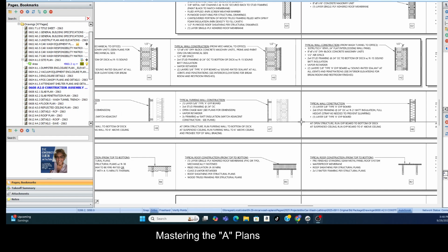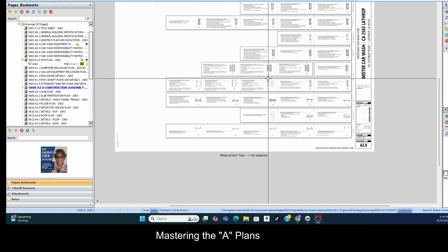And what we're going to do as the framer, what do we have to do? The floor plan is going to give us how many linear feet we have of each type. But then we have to look at a section view, right? The view where we cut it in half and we can see it from top to bottom so we can determine the height of the walls. And that's what we want to do. So for the framer, they definitely need the plan view. The view from above helps to measure accurately how many linear feet of each of these assemblies we see on the floor plan. But then we have to find a section view that we're led to as well, so we can determine the height.